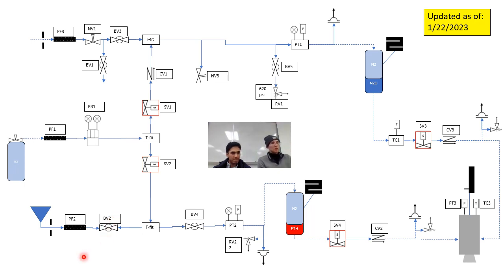It's going through the particulate filter, through VV2, and running toward that run tank that you see with nitrogen and ethanol in it. As soon as you're done, close VV2. Then close VV4 and SV2. The run tank at that point is just above atmosphere, just like we had it set from that pressure regulator.